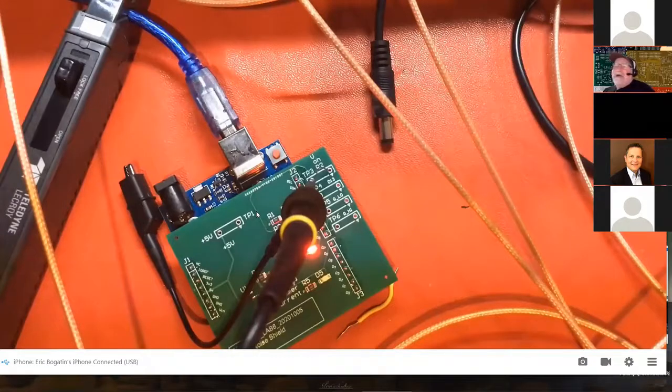And it's the combination of the bandwidth of the probe and the bandwidth of the scope. And it's not just the sum, it's 1 over the square root of the sum of the squares. And so you want the bandwidth of the scope to be about twice the bandwidth of your probe, and the bandwidth of your probe to be about twice the bandwidth of your device. And that limits the influence of the system.